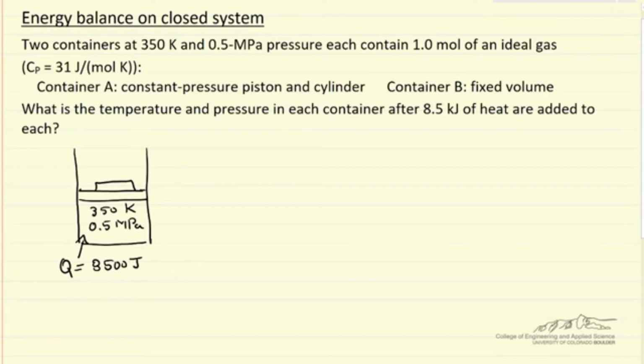And so the first law, closed system: change in internal energy is heat plus work, and the change in internal energy is CV delta T for an ideal gas. Independent of the type of process, that is equal to Q, of course, a fixed number. Work is minus pressure times the volume change.